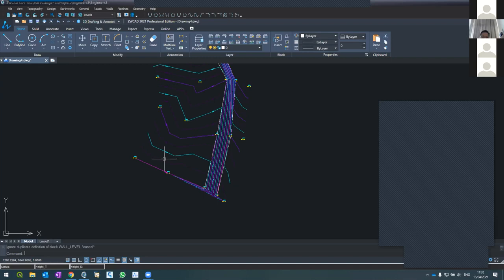After the cut and fill has been done, meaning we have the surface before, now we'll create another surface which is after. And then we'll tell the software compare the two surfaces. So again, imagine this is one surface, right? Now we will take points of what happened after we finish the earthworks. We create a surface out of it. And then we'll tell the software give us the volumes between these two surfaces. How to do it?